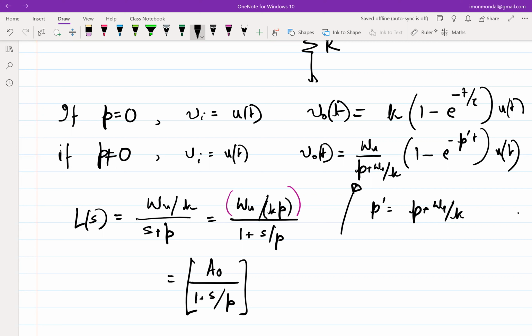And in case of an ideal integrator, you are getting this. So in case of an ideal integrator, what is the phase of the loop gain? How will it look like? 90, minus 90, right? So it will simply be minus pi by 2. Good. So now in case of a real integrator, how will it look like?